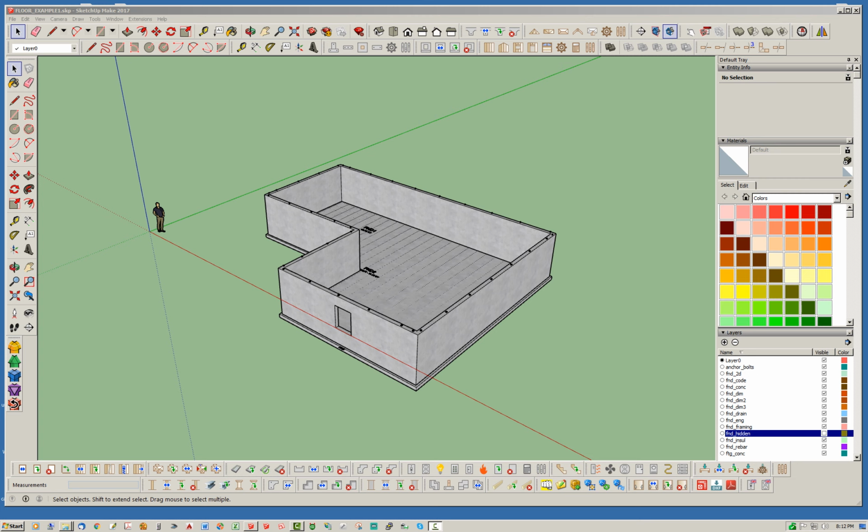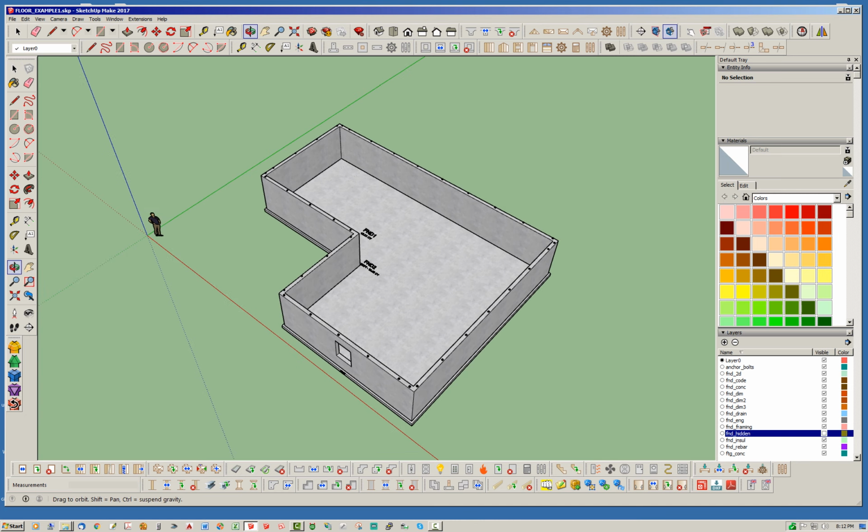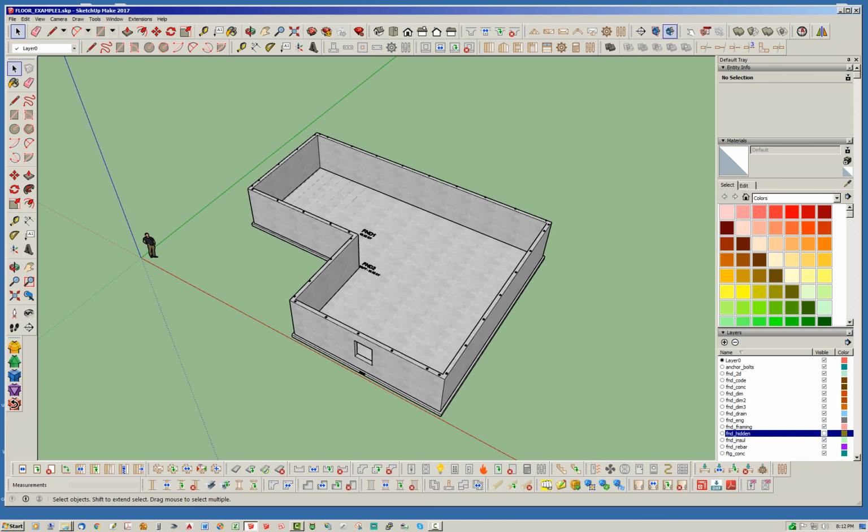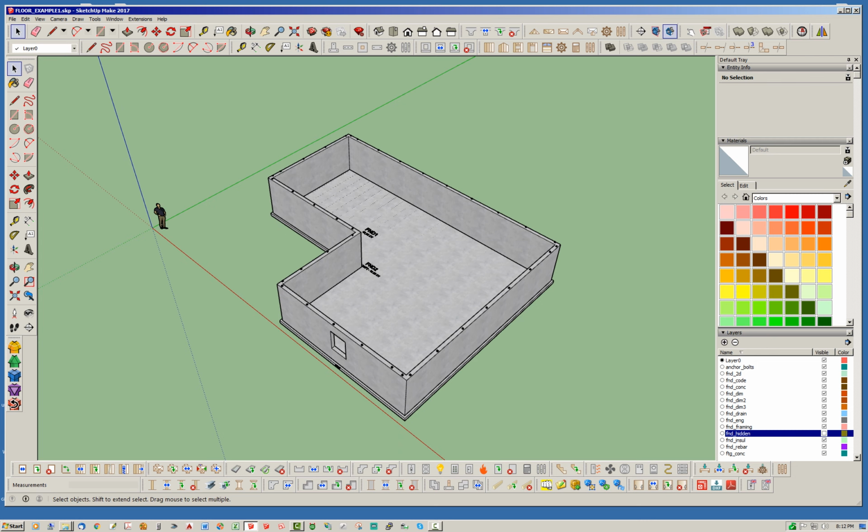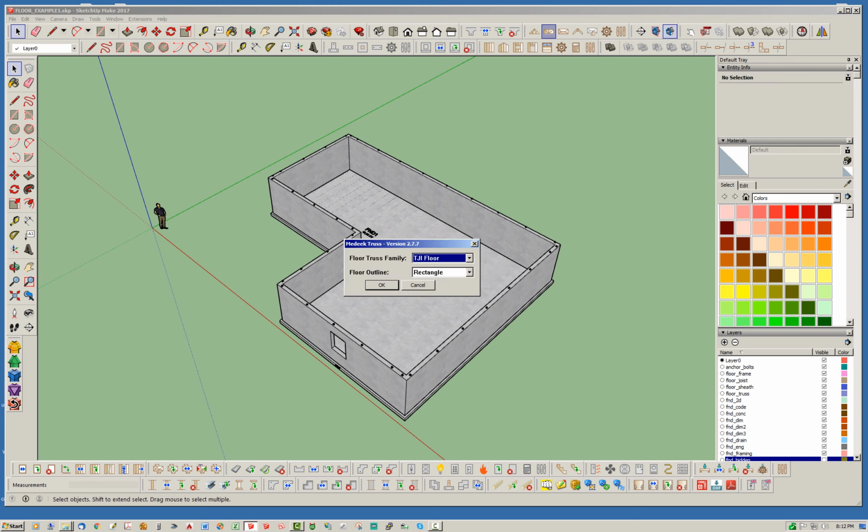Wilkerson, and today we're going to be talking a little bit about what I call Polygon floors with the current floor module of the Truss plugin. As some of you know, you can draw TGIs, floor trusses, lumber floors using the floor truss module. However, the problem right now is that we cannot actually do polygon floors, even though it's showing it can have that option.